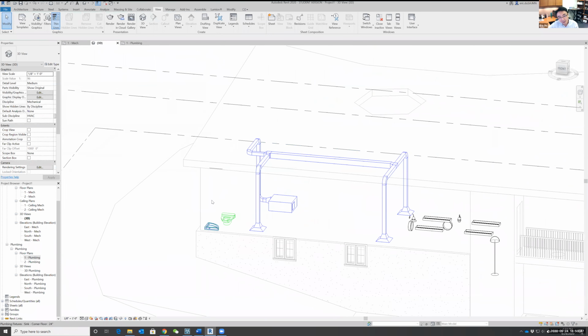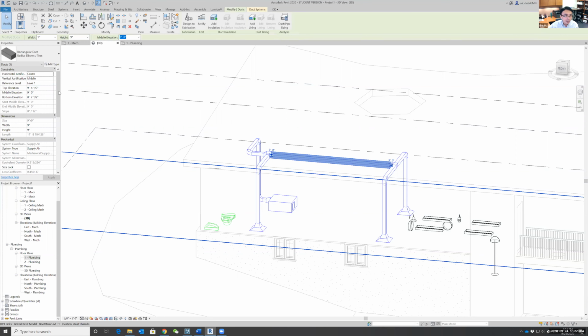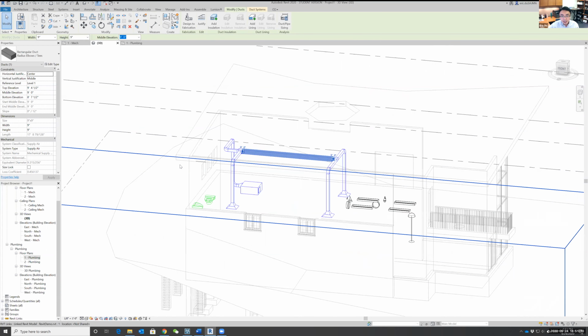All right, I guess we need to change it to a bigger room, and you will definitely see the water line also automatically sketched by Revit. And once again, if you want to change the parameters, you do not need to manually replot that. You can always select anything and just change the parameters, the elevation, for example, of that, and Revit will take care of the rest. Okay.